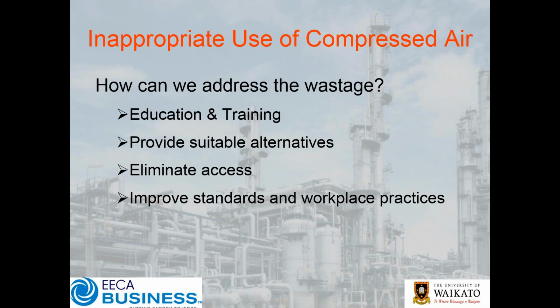So Tony's question is, is using compressed air to produce a vacuum a cost-effective solution? Well, the short answer is no, typically. If you're generating a vacuum, you are generally going to use probably 3 to 4 times the energy, depending on the application, to generate that vacuum with compressed air as opposed to a dedicated vacuum pump. It's something that in future webinars we'll go into a little bit more detail. Today's really just about a general overview, but no, it's a very good question.